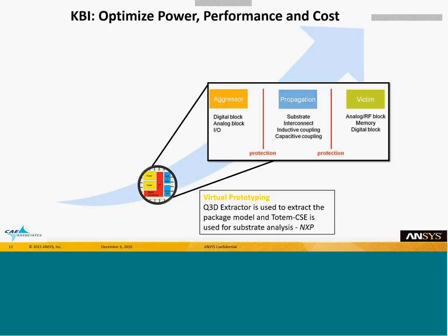After you create the chip, then you're going to need to connect to it. Whether you're going to use wire bonds or some sort of leads that are coming out of your chip, you're going to need to package it up. And maybe you're going to need to know what is the R, L, C, or G, right? You remember resistance, inductance, or capacitance. And so we would look at a cross-section of that part, and we would use our Q3D Extractor here.